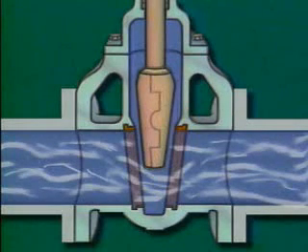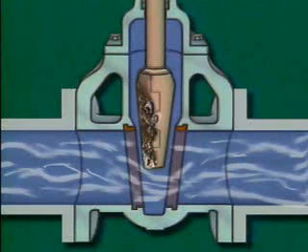Also, the flow of fluid through a partially open gate valve wears the disc unevenly. In time, the edges of the disc that are most exposed to the flow become eroded, and the disc can no longer seat properly.